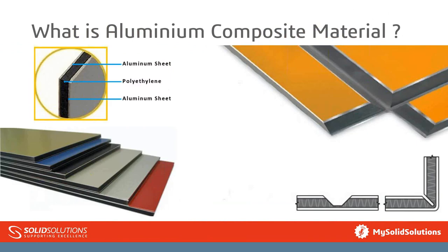And moving back onto the slide I was on a second ago, just talking about how we would produce this, because obviously it's a folded sheet metal component, but on the other hand, in Solidworks sheet metal, we can only work with a uniform thickness, and obviously this has multiple thicknesses, in fact could even be multiple bodies. So how are we going to produce that in Solidworks?